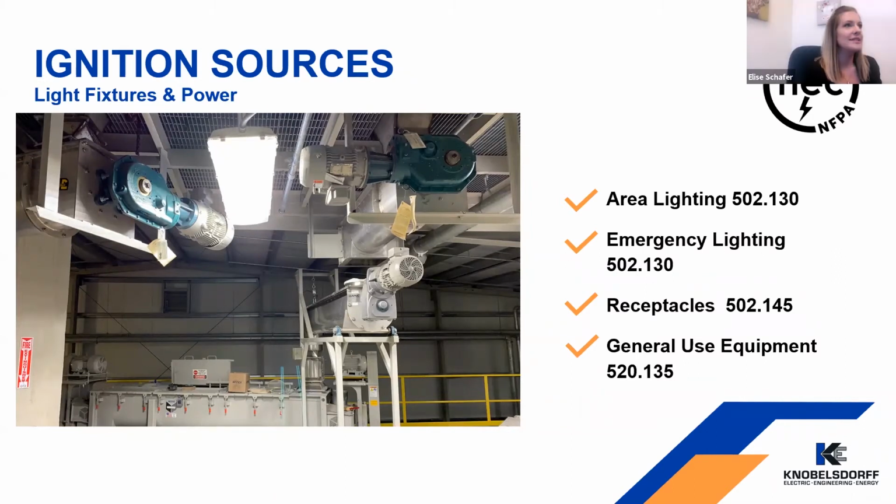Yes, Carl, I was just gonna jump in here. So we have a user who says that in Class 2, Division 2 locations, he has not found hardly any motor manufacturers that will confirm that their case temps will not exceed the allowable temp of the NEC. We have often had thermistors or temp devices added to the TEFC motors to assure that the case temp is not exceeded. What is your experience?